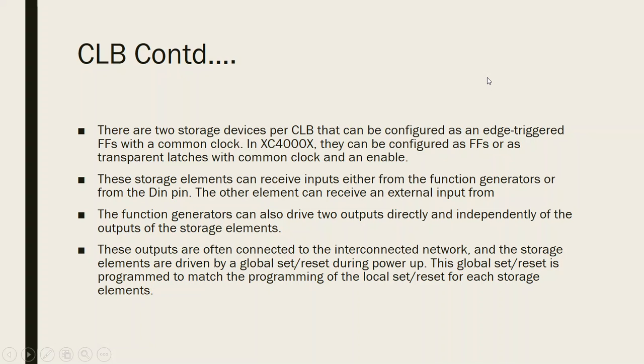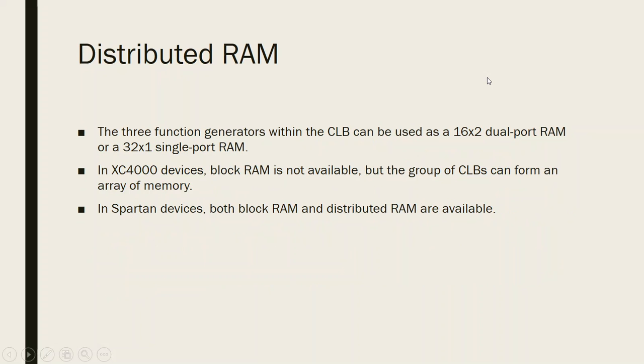So these storage elements are often connected to the interconnect network, and they are driven by a global set reset during power up. So this global set reset is programmed to match the programming of the local set reset for each storage element to maintain synchronization.